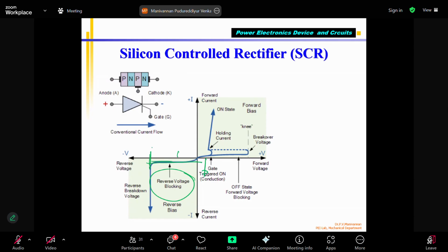But once the voltage reaches minus 40 volts, for example, or plus 40, breakdown happens. Breakdown happens on both sides. Correct? So if you buy an SCR and the manufacturer says the breakdown voltage is 40 volts, you should operate at less than 40, in both directions. Okay, this is called the reverse bias direction. Because of these two properties, reverse bias and forward bias, we are able to use the SCR similar to a diode as a rectifier. We will see that.